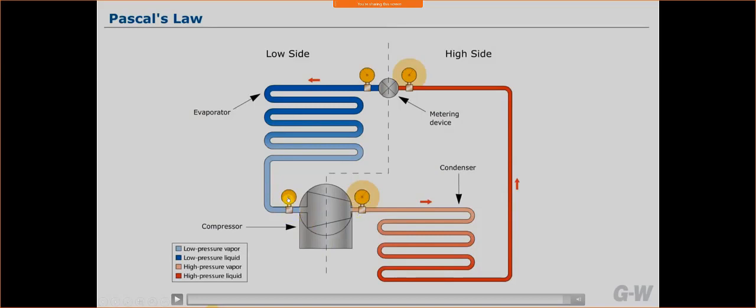So we've got a low pressure here, we'll say 60. Over here, we've got 120. Then we come back through here, it gets nice and hot, and comes back over with that high pressure. We go through a metering device. The pressure drops, and we have cold refrigerant. Real basic. We'll definitely cover how this really works in more detail in a sec.